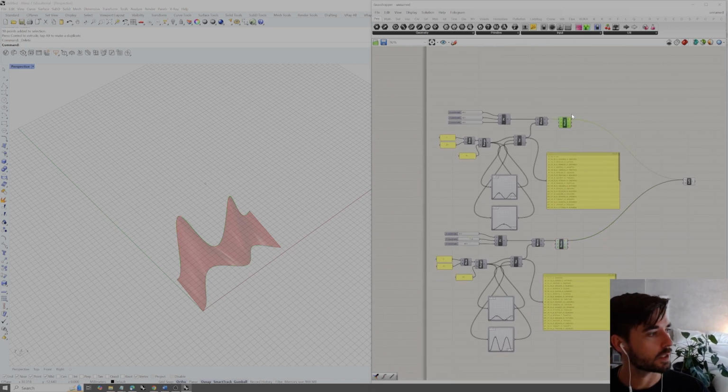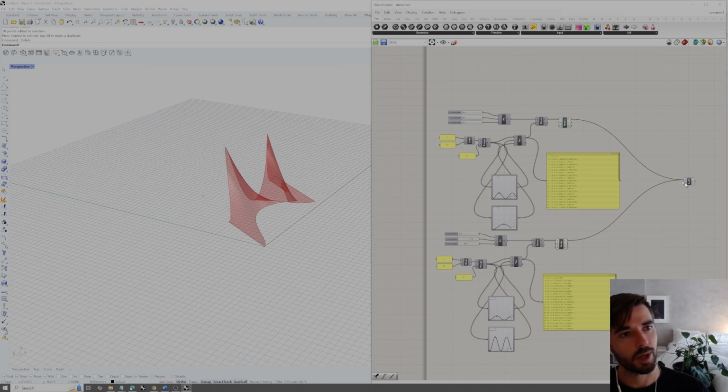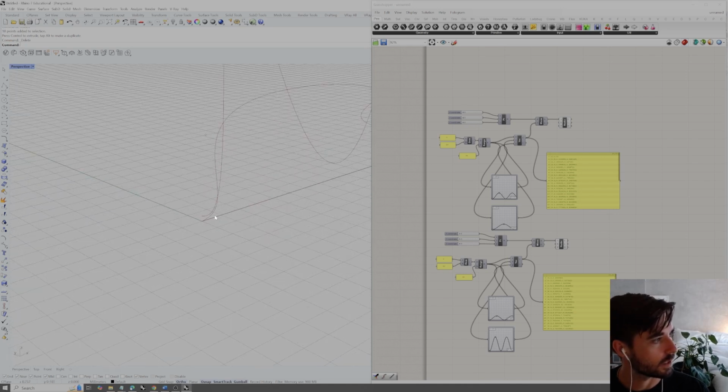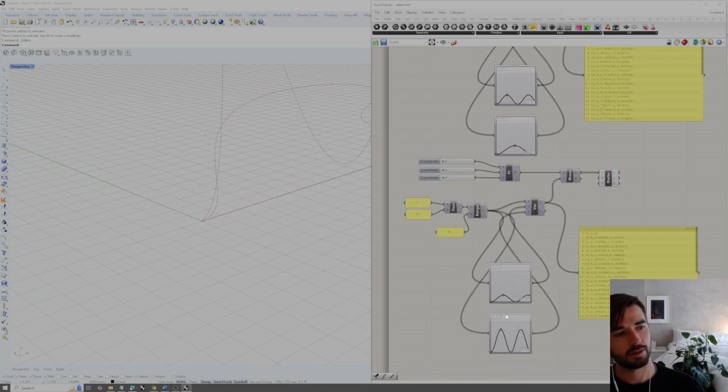So we want to use this first geometry as our rail curve, and we can go ahead and delete this loft component. And we actually want these starting points to be exactly the same. So 0 for both. And we can now see, okay, that second graph just had gotten lifted up.